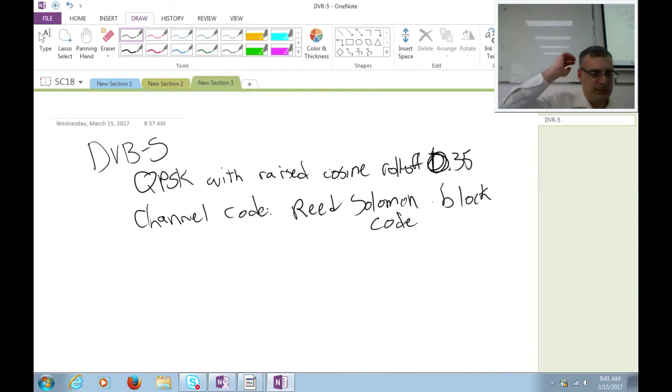Anyway, the Reed-Solomon code is a block code, so that means it operates on blocks of data, taking n code bits in and outputting another k code bits out, for example. K is always greater than n in that instance. And you therefore increase the amount of physical or coded data bits compared to the actual raw data bits that you're sending.